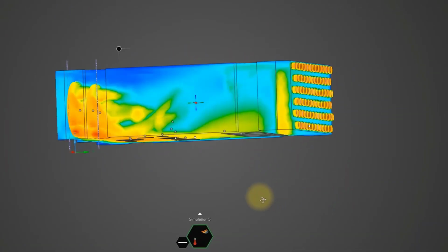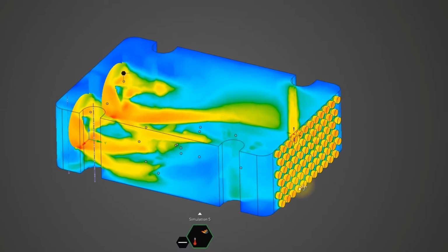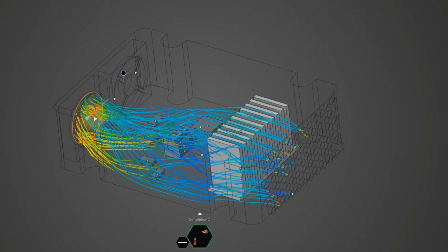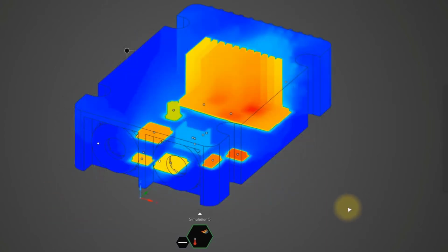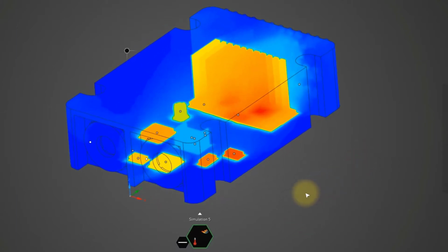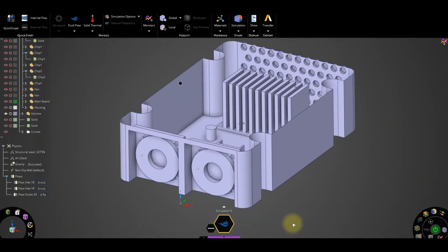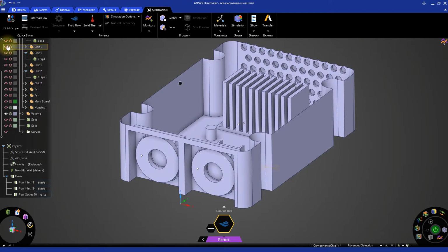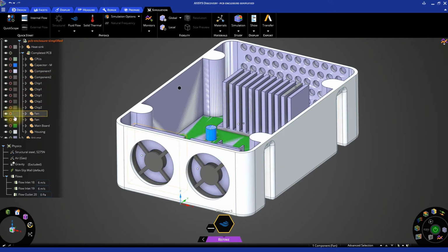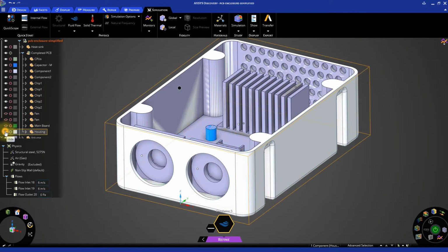The Refine stage allows us to perform a conjugate heat transfer simulation. This kind of simulation lets us combine the fluid dynamic analysis with the solid thermal analysis, and will allow us to accurately predict the temperature that each component of the PCB would reach while operating. Use the model tree to show the completed PCB and heatsink. Then, hide the fans, board, housing, and the extracted volume.